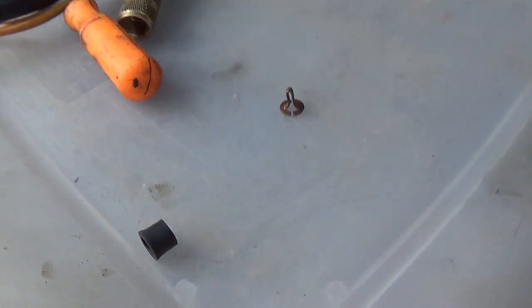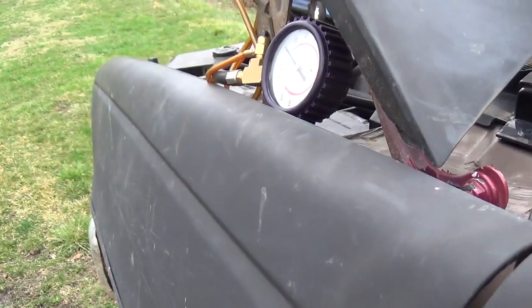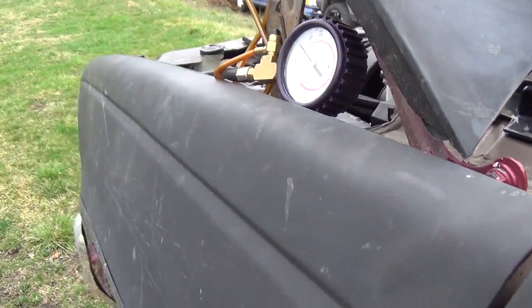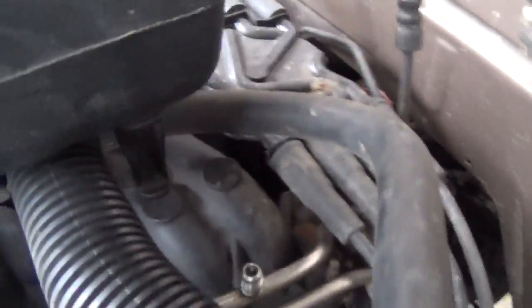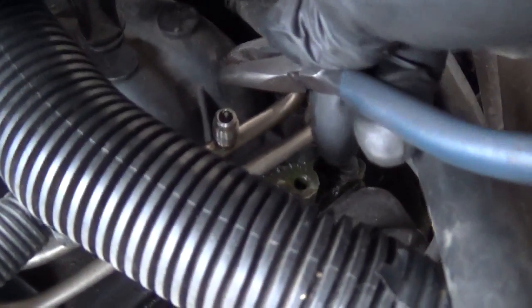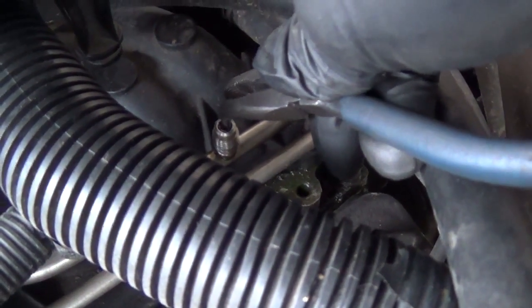and just make sure we have good fuel pressure. Alright, I got the fuel pressure gauge reinstalled. Let's see if... still doesn't work. Alright, now I see the problem. The little Schrader valve inside the port here is messed up, so it wasn't my gauge.